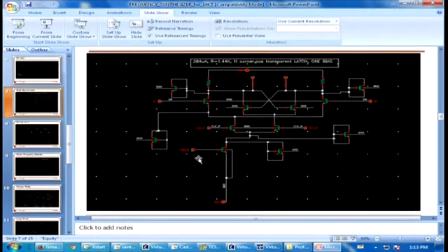Because it is always burning the current. It is a current logic. It's not CMOS kind of logic. It means that the swing of the voltage is not from the ground to the power supply. The swing of the voltage is halfway around. Let's say I am having a power supply of 1.2 volt. So CML logic will generally go from 0.6 volt to 1.2 volt. It means if it is 0.6 volt, it is stated as logic 0. If it is 1.2 volt, it is logic 1.